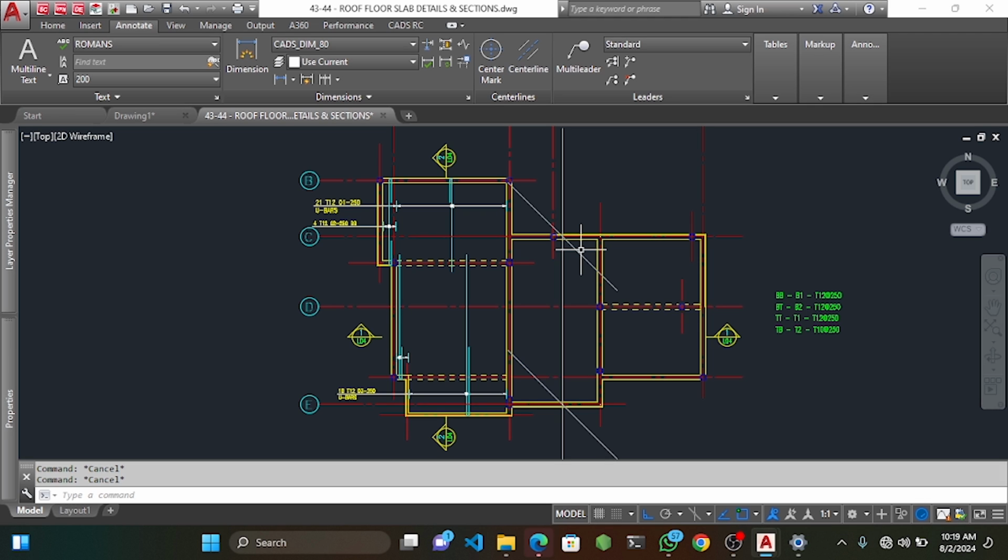I take it to like 11.4, so I don't go beyond 11.4 meters when I'm assuming the length of my bars. So for this one now, this panel alone is about 7.6 meters. So what I can do, I can just draw like 2 U bars in this panel.